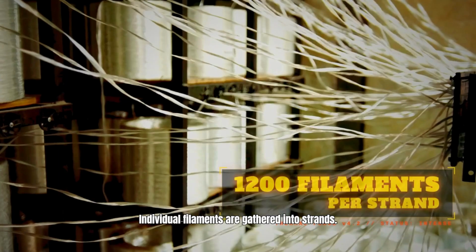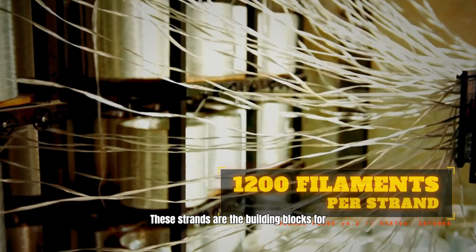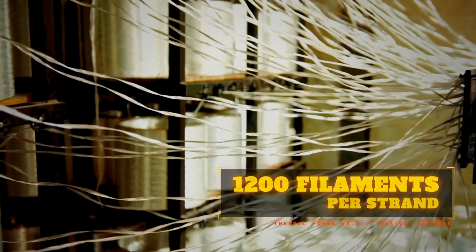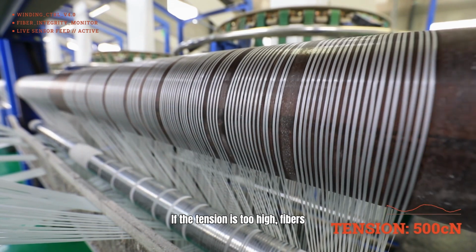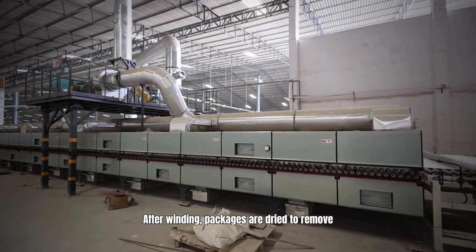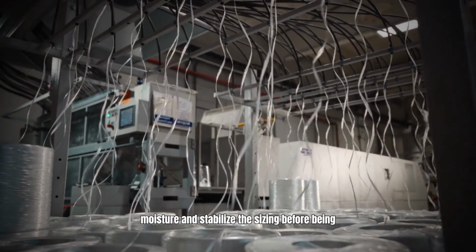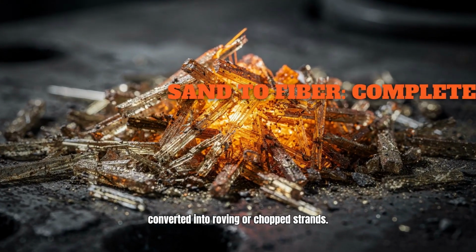Individual filaments are gathered into strands. These strands are the building blocks for every fiberglass product. Winding must be perfectly controlled. If the tension is too high, fibers may be damaged; too low, and the package fails. After winding, packages are dried to remove moisture and stabilize the sizing before being converted into roving or chopped strands.